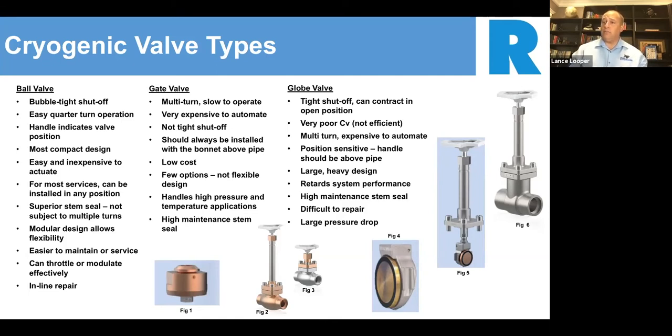But it is good for pump applications. If you guys have any cryogenic pumps and you need that full flow going to the pumps, it's fantastic. And also any kind of plant applications, I'd highly recommend a gate valve. Easy to maintain, very difficult to repair if you do not follow the instructions. And I'll get into that a little bit later on in the presentation.